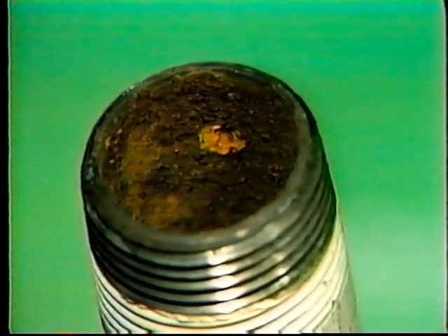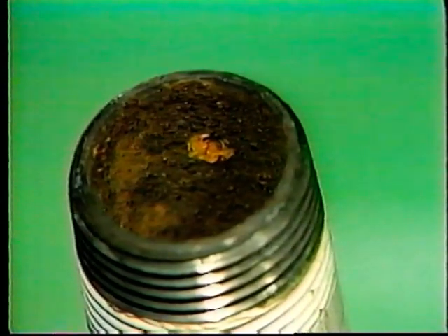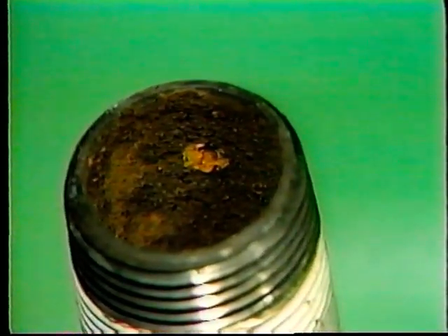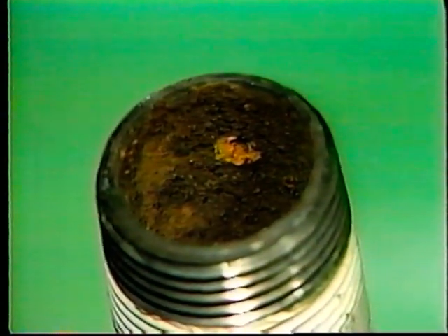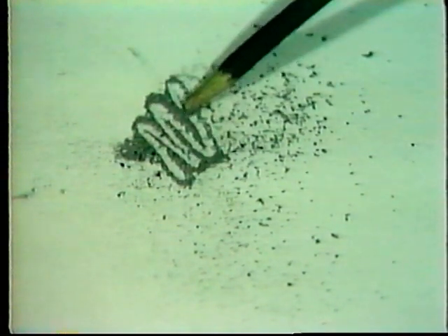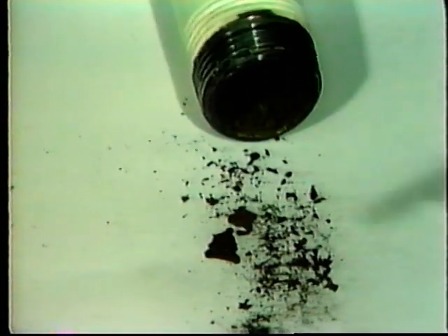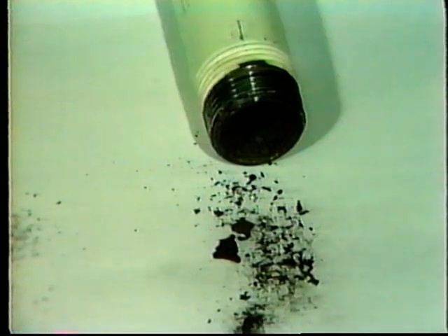The second source of contamination is dirt generated within the system during use, like this rust. Or as a system operates, moving parts begin to wear and often generate small wear particles. When these flakes become loose, they get carried downstream by air pressure and can jam valves or damage pneumatic tools that might be used in the system.